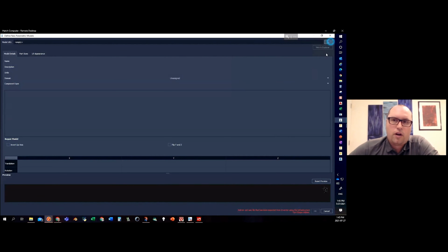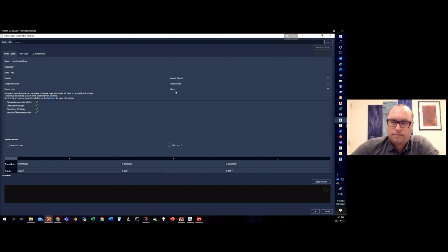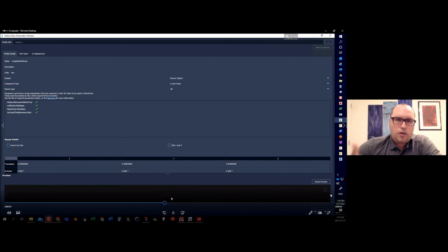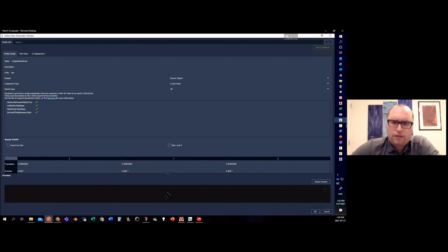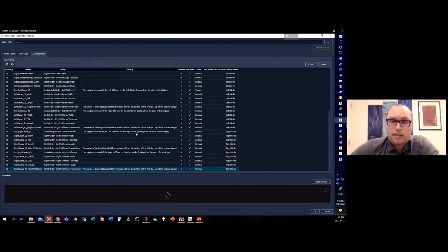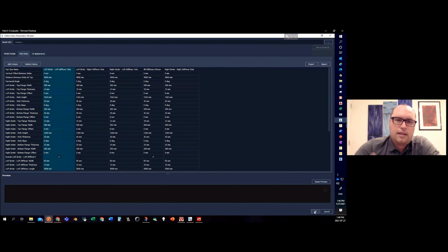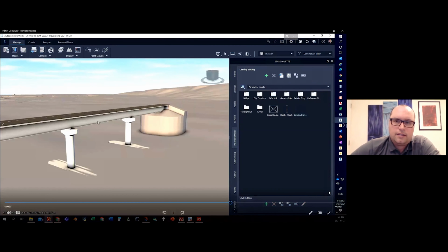If I put the stiffeners that I put in onto the generic cross beams, they just wouldn't interact with each other because they would have different parameters and they wouldn't see each other. So you put the component in and then you label what type it is. There's a little previewer at the bottom, but it's garbage. And then here I'm showing us importing the JSON files that we created with our app. And it brings in all the tooltips and the labels nicely. And then same thing here, it pops in all the sizes.